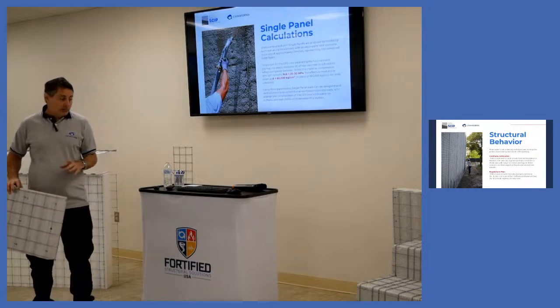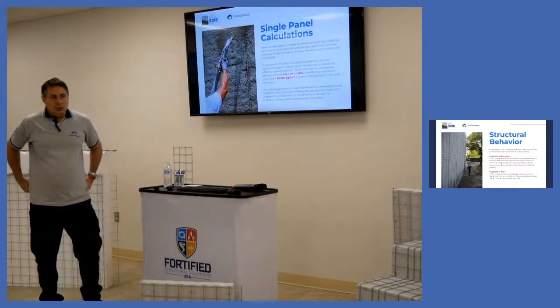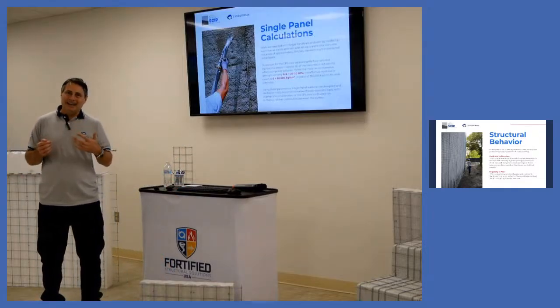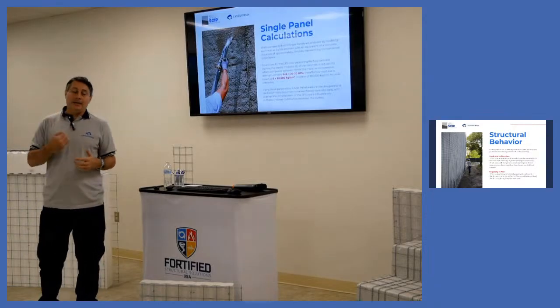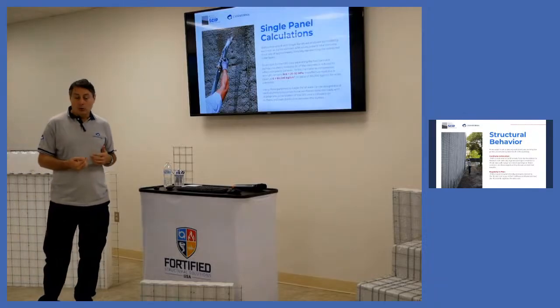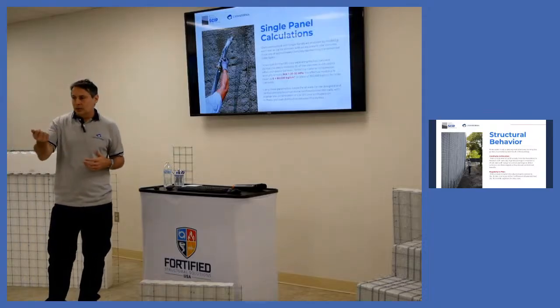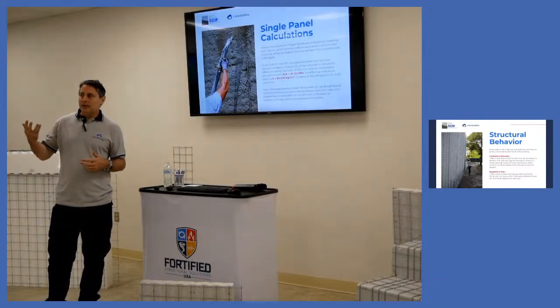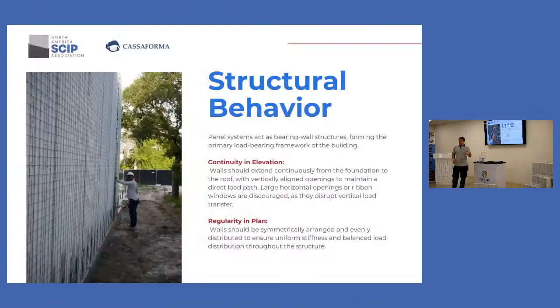Can you make more than that? Yes, you can. The problem is that mortar is not the cheapest thing, and you are also adding more loads. You have to understand that you can only apply 1.5 inches at once. There's a limit, and the first layer will attach better than the second, because the first layer deals with the waves of the panel.